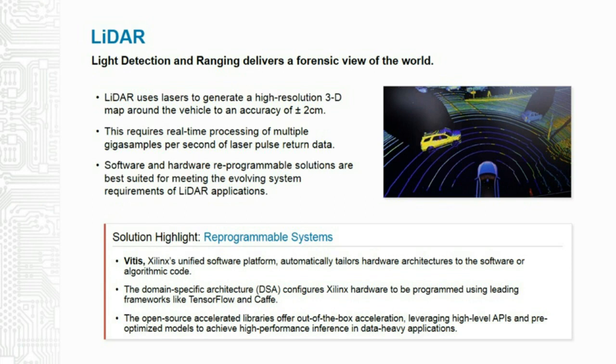It also requires a very big amount of processing power because it's getting up to 1 million measurements every second, and these have to be translated into actionable data. So if you're using LiDAR, you're going to have big-time computing power to go along with it. The reason that LiDAR is appearing on prototypes and working models of self-driving cars is they need the computing power anyway. So it's going to be there for that kind of vehicle, but is not currently available in a commercial vehicle that you drive yourself.